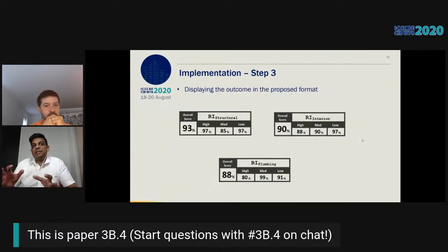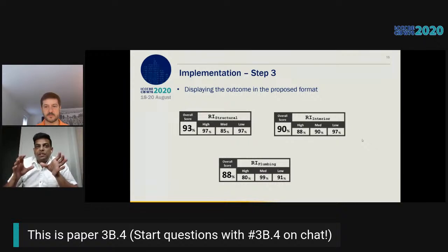And finally, this is how the actual calculated score looks. These 3 tables show the certification outcome of the same tool. I repeat, the same tool from the perspective of 3 different disciplines. If you look at the high conformance, high importance columns, it clearly shows that the tool is more accurate for exchanging IFC elements related to the structural discipline than elements related to a plumbing discipline. Thus, a structural engineer could proceed with data exchange with this tool, even if the other columns show less accuracy.